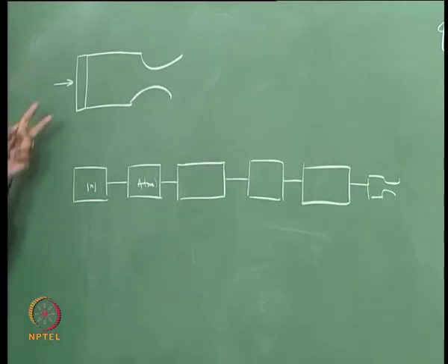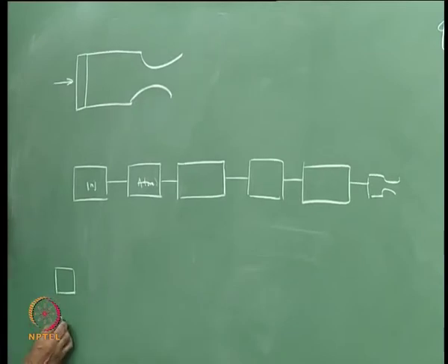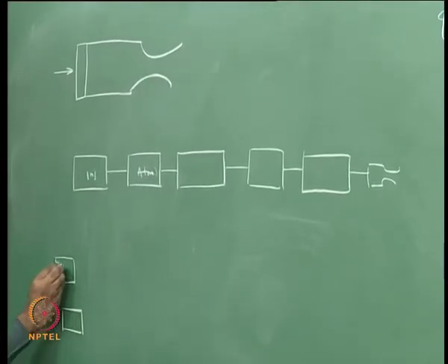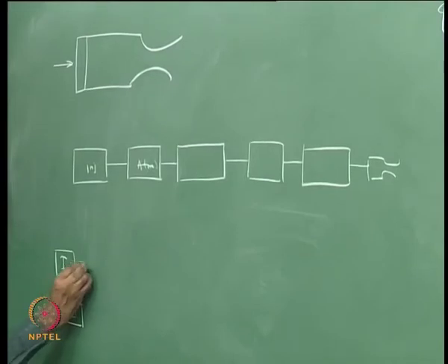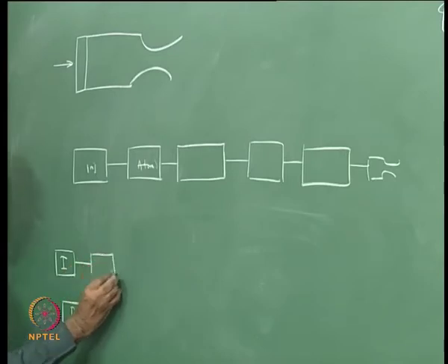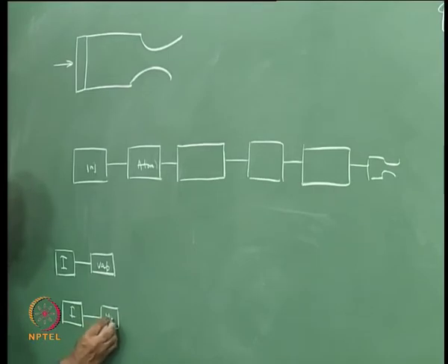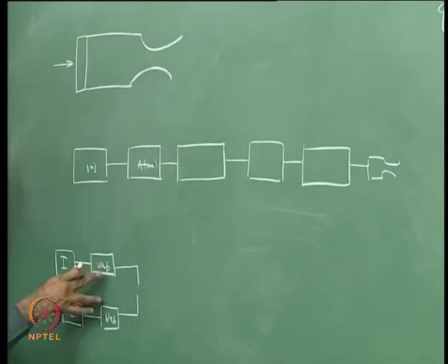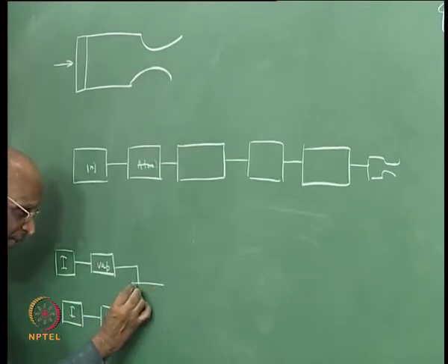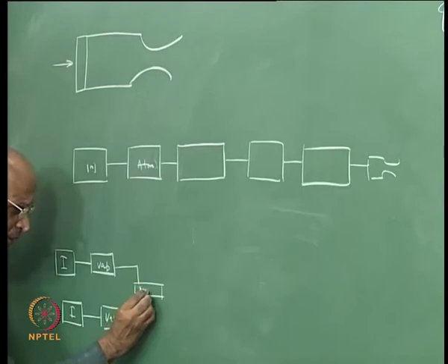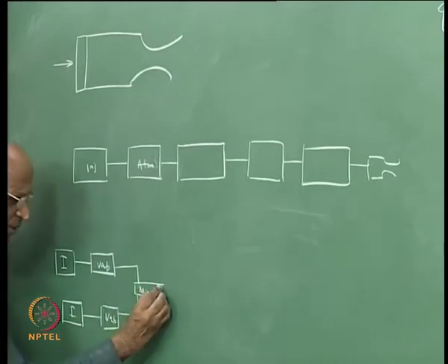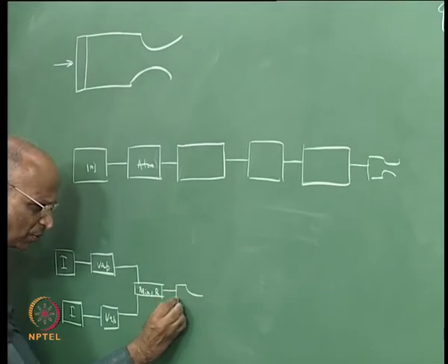Now in a bipropellant injector, that means when I have fuel and oxidizer, maybe I have a fuel injector, fuel holes, I have oxidizer holes over here, I call it the injector over here. The fuel injector maybe creates the fuel drops and it vaporizes first, the oxidizer drops vaporize, the vapors come and mix in the chamber, and there you have mixing and reactions taking place over here,